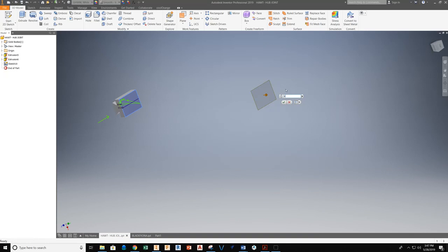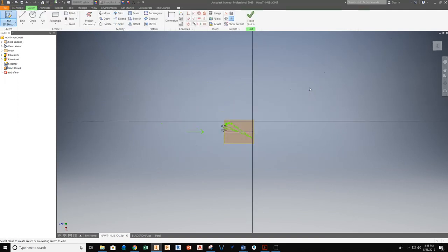So I'm just going to go ahead and set this up and just say 9 inches for the sake of design here. Not sure what the actual measurement should be, but I'm just going to set up 9. You guys can check that measurement before you design. And I'll go ahead and do a start 2D sketch, and I'm going to place it on that work plane.